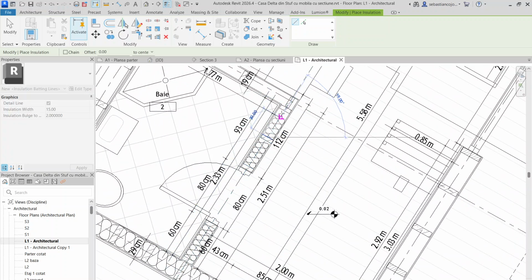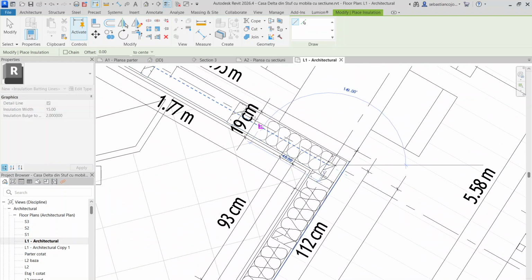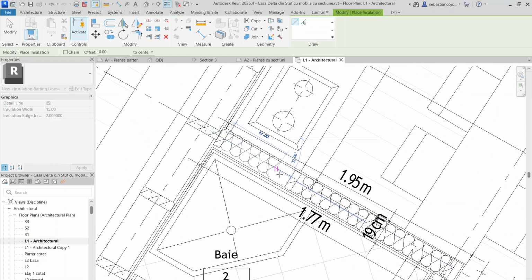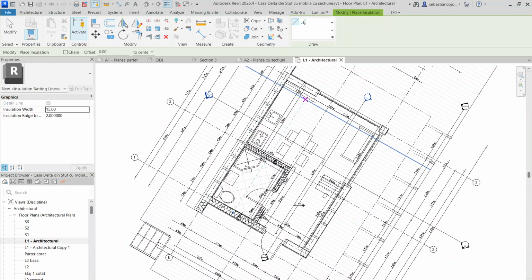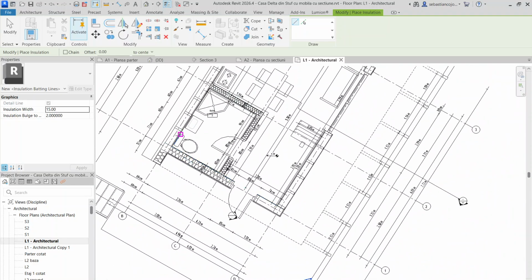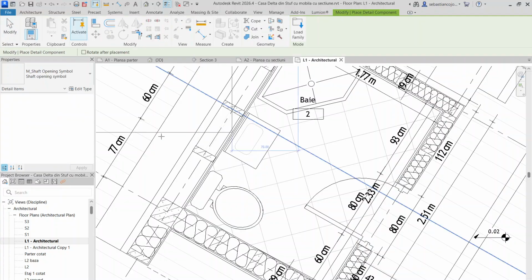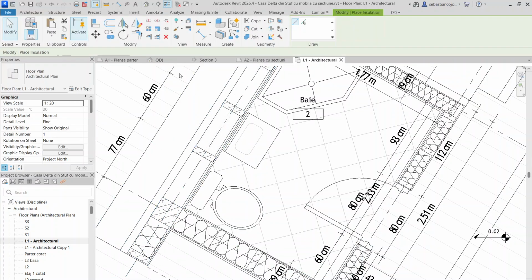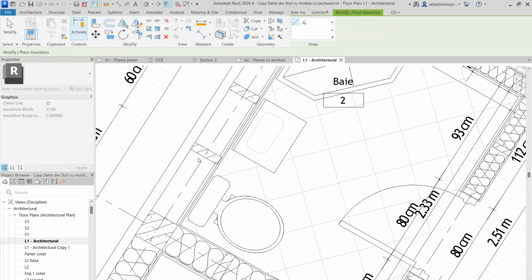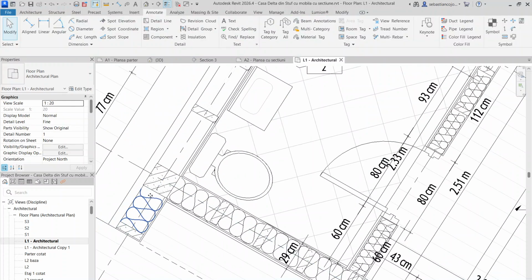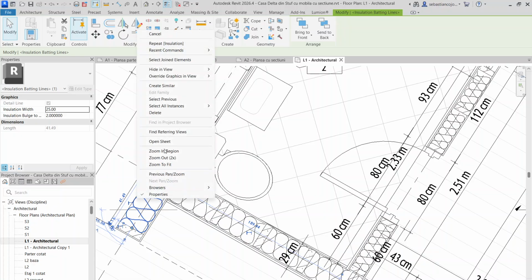And now you can put your insulation annotation. Unfortunately, this is a 2D aspect. There would be a workaround if you do not need this annotation so much. If you're, let's say, US based, you can also find some sort of hatch pattern, and I'll show you in the menu after I finish here. There is a hatch pattern with hexagons, and that would be appropriate for insulation, that kind of texture with hexagons.